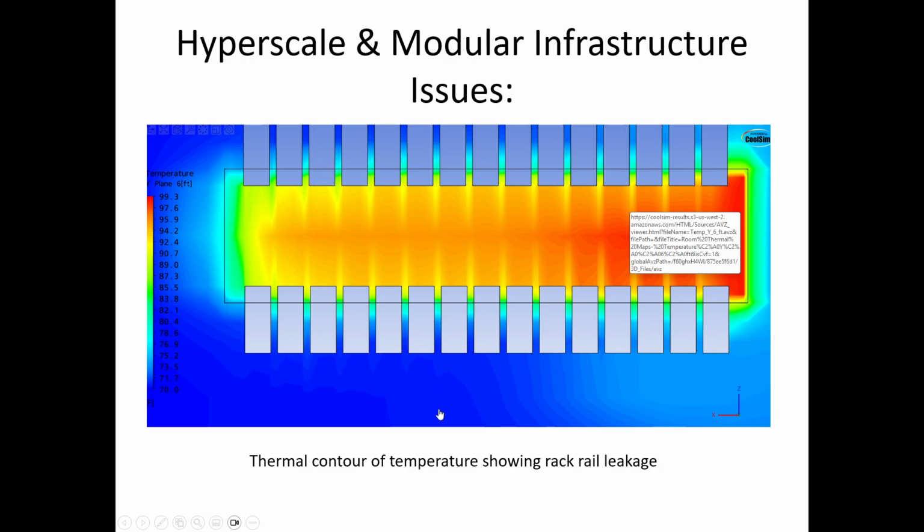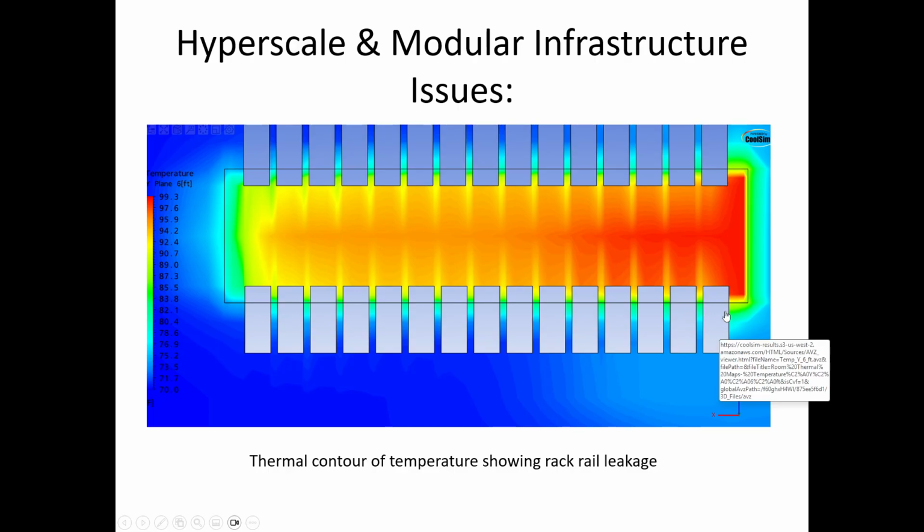So it manifests itself in the thermal characteristics of the room. If the pressure deltas aren't correct, you'll get leakage. That's what we're seeing along this edge: leakage. This is leakage from the hot aisle into the cold aisle through the surfaces that seal the IT servers against the rack. Right here you see leakage. You see it's starting to poke out. It's bleeding out because we don't have enough positive pressure between the cold aisle and the hot aisle. So the hot aisle is very hot, creating high pressure, and you've got velocities going to 0 in there, creating pressure, and it causes this to occur.